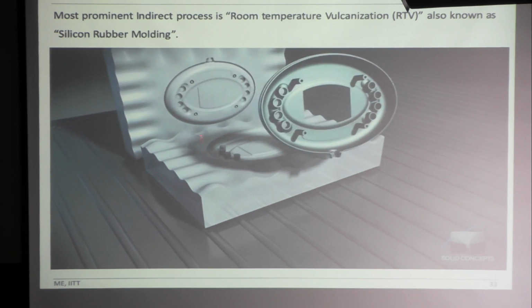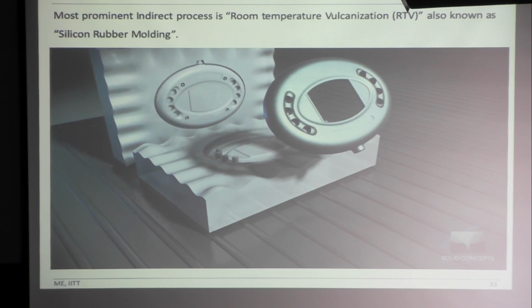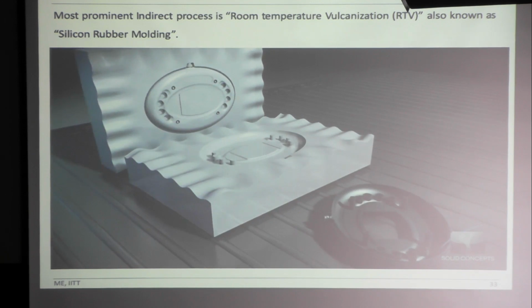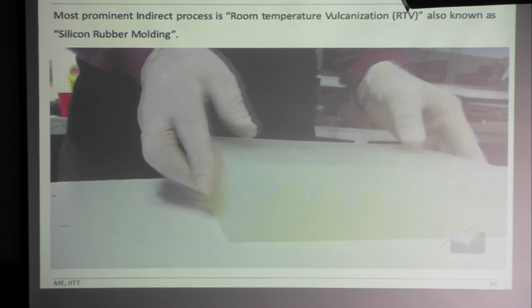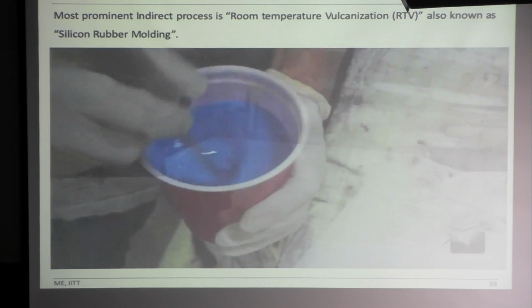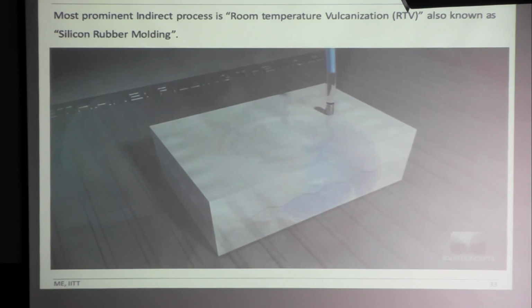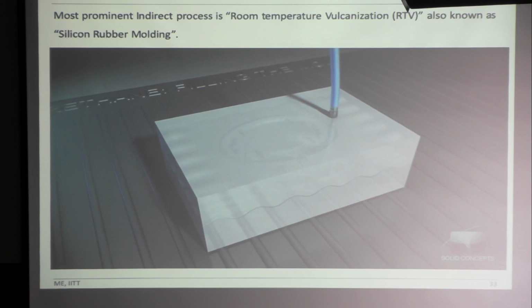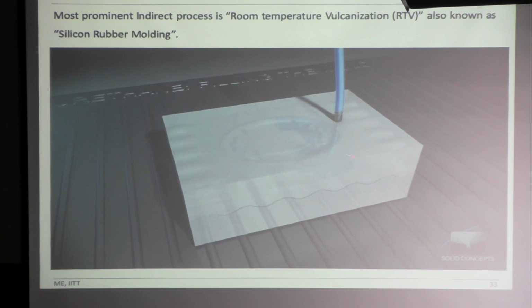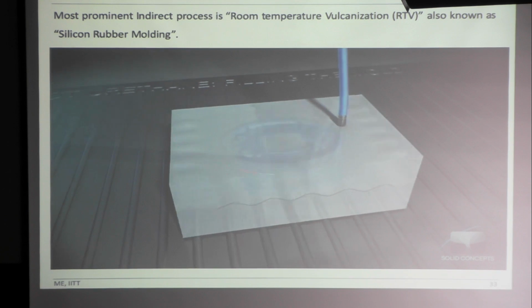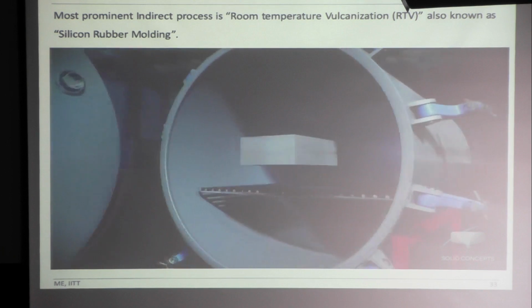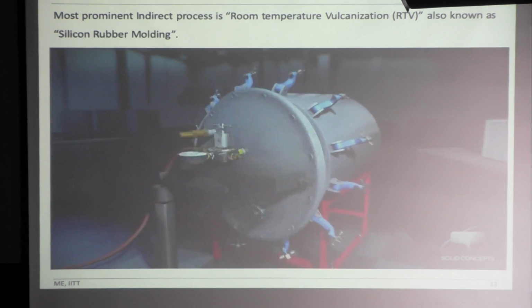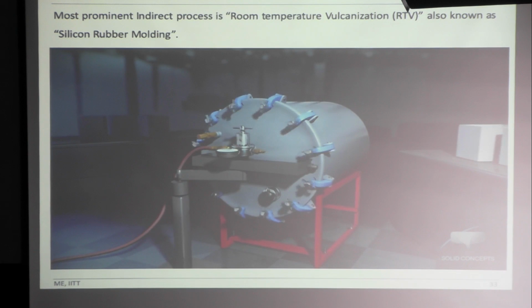So this is the cavity. Now you use this cavity to produce multiple components. You pour the polyurethane material, mixed with different colors, and manufacture the component. So now we are pouring the polyurethane material, it is being filled within the cavity, you bake it at around 70 degrees centigrade for around 3 hours, and then you take it out.